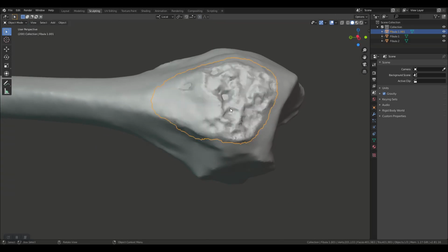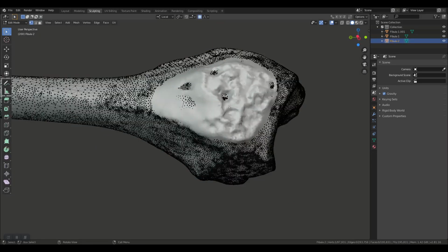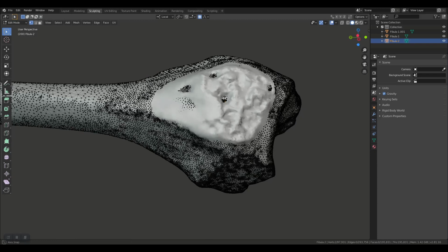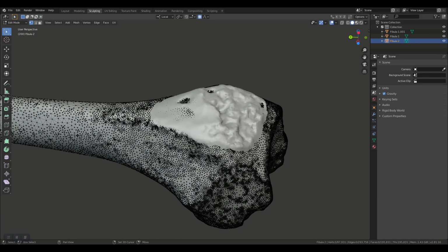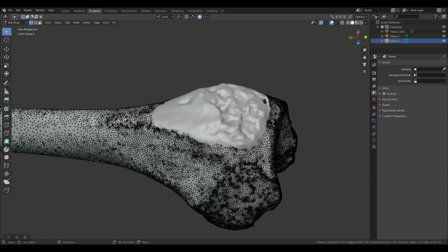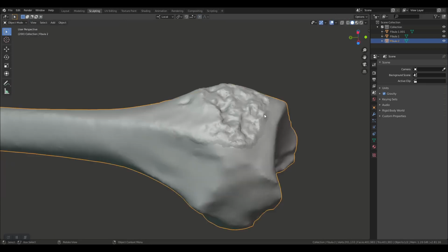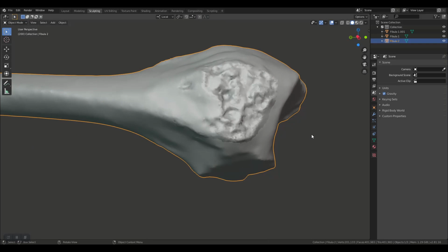After positioning the new geometry, we might see that the surface of the low detailed mesh is too flat and covering the new geometry cavities. To resolve it, just select the low detailed geometry and move it down using proportional editing by pressing the O button. After both pieces of the mesh are ready, go to Object mode for composing them